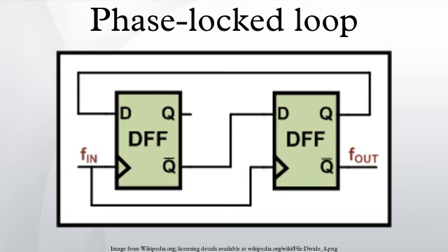Modeling, time domain model. The equations governing a phase-locked loop with an analog multiplier as the phase detector and linear filter may be derived as follows. Let the input to the phase detector be f1(θ1(t)) and the output of the VCO be f2(θ2(t)), with phases θ1(t) and θ2(t), and functions f1 and f2 describe waveforms of signals. Then the output of the phase detector is given by: